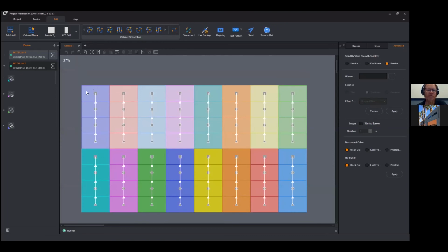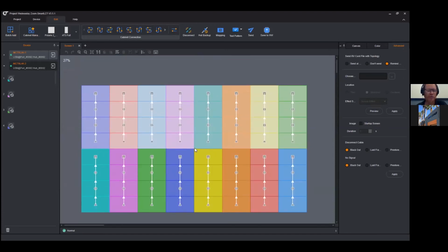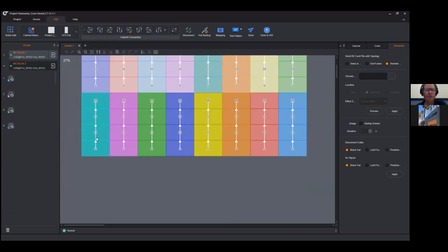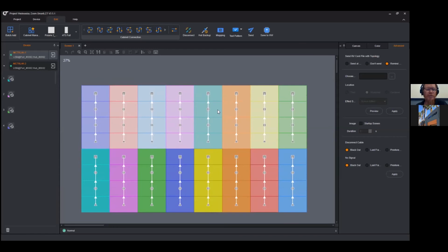So I wired them vertically. So that port is 480 pixels wide. If I did two of them, they'd be 960 pixels wide, and I could not turn on sender low latency. So that's sender low latency. In order to turn on receiver low latency, I'd have to have an A8 or an A10S receiver card. And this is just a generic file, so it doesn't actually have a receiver card associated with it. So I can't turn on receiver low latency.